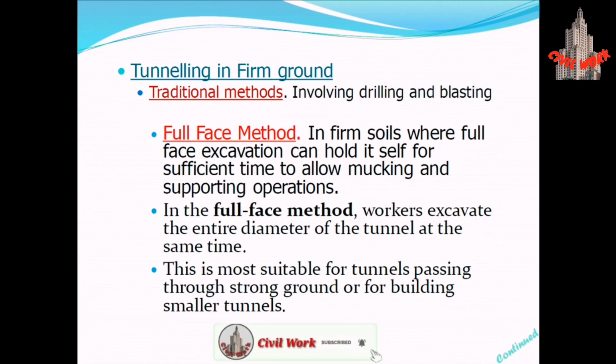full face method. The full face method is a tunnel excavation technique where the entire tunnel face is excavated simultaneously without dividing it into smaller sections. This method is also known as full face tunneling or full face excavation method. Now when we have the firm ground, which is also known as stable ground, we don't have to pay so much attention towards the safety of the excavation.